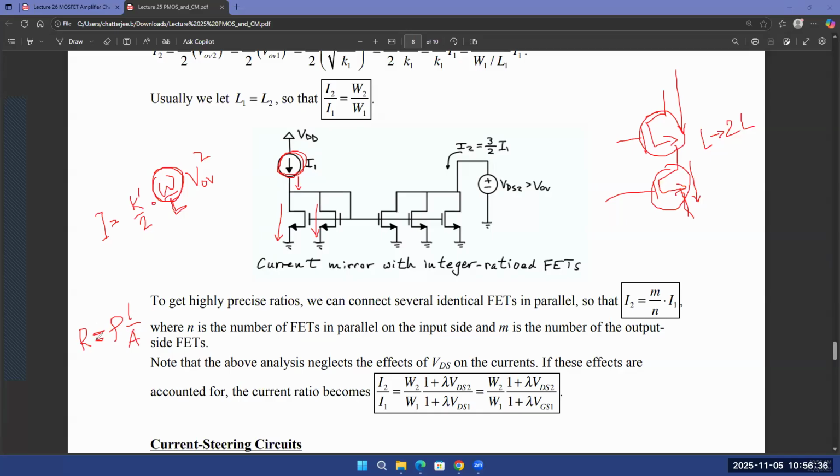If your resistance is getting halved, your area is getting doubled, and area will get doubled if either your width gets doubled, or the third dimension, which we generally don't draw in the 2D picture of the MOSFET, is getting doubled. But that is not there in the equation. So of course, you have W and L. So if your resistance is getting halved, your width is getting doubled. That means your current is getting doubled, and that is synonymous with saying your resistance is getting halved.